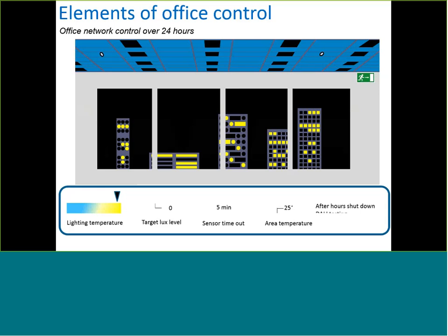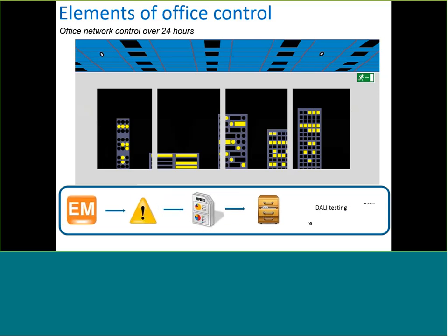Once this is done, the system can automatically go through and test the individual light fittings using the Dynalite protocol. This allows us to turn on each of the individual fittings and monitor its status. If there is an issue, it is then escalated to facility management in the morning. We can then save this as a report for ongoing performance of the system, which can be archived for later reference. Emergency lighting at this time can also be tested.